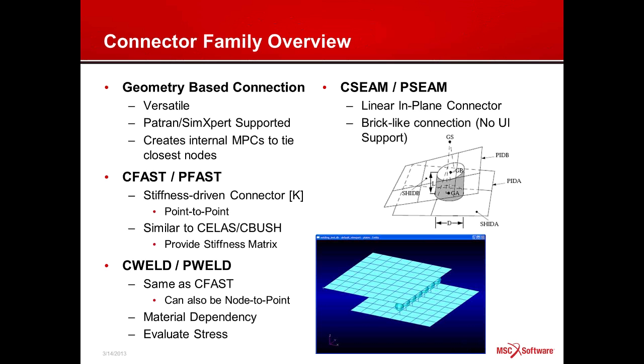The trick here is that they only rely on a position in space. If you look at the little quick reference guide diagram here, the GS location can be defined as a point, a geometry, or a node inside your model preprocessor like Patran. Once that point location is defined, regardless of how the mesh density is distributed for the two plates you want to attach together, it will make a projection to GA and GB. From that point, it will create the connector inside the solver architecture. So you will not have to worry about defining or creating the elements per se.